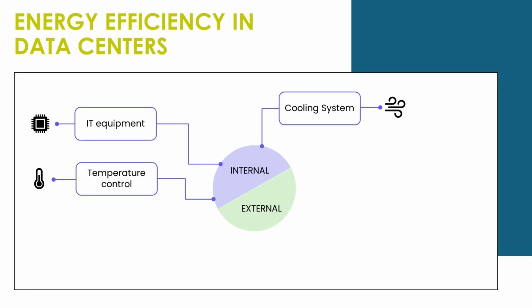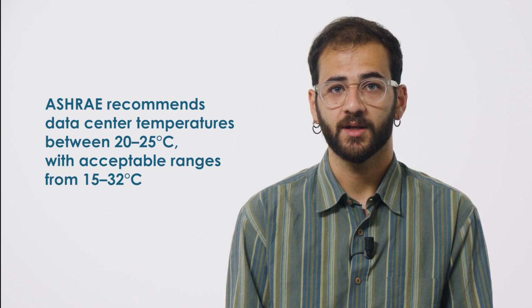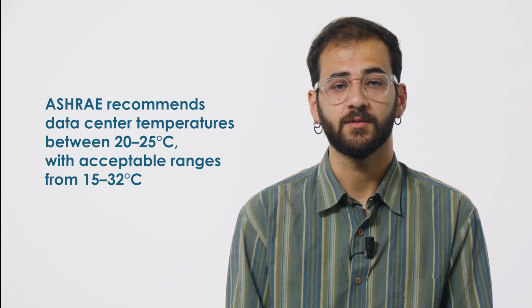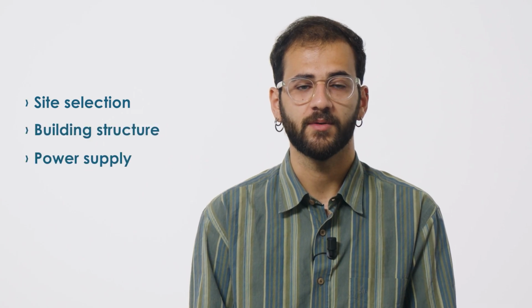Temperature control strategies also impact the energy use. Raising the set point for the data center's internal temperature can reduce cooling demand. The thermal gradient between the indoor and the outdoor temperatures drives the cooling load. Data center temperatures between 20 and 25 degrees, with acceptable ranges from 15 to 32 degrees, are recommended. Let's now analyze the external factors affecting energy efficiency: site selection, building structure, and power supply.